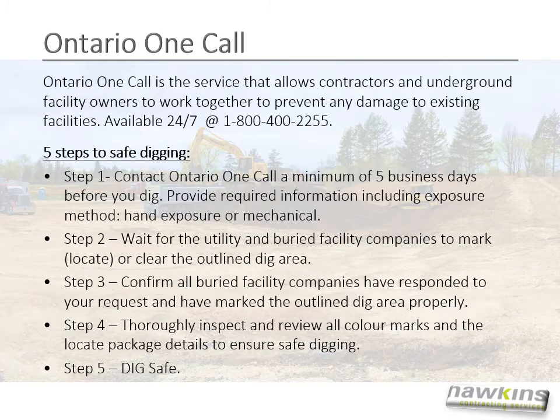The locating and marking process usually involves contacting Ontario One Call. Ontario One Call is a service that allows contractors and underground facility owners to work together to prevent any damage to existing facilities. They are available 24/7 at 1-800-400-2255. And as per them, there are 5 steps to safe digging.